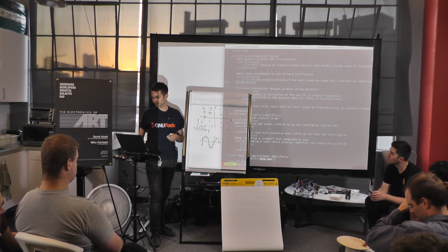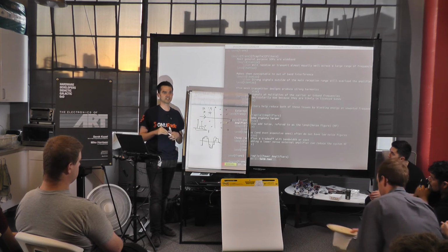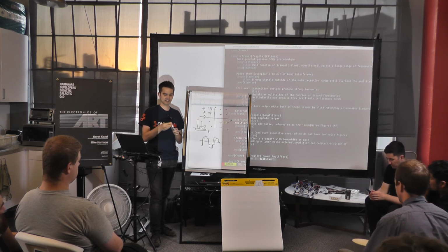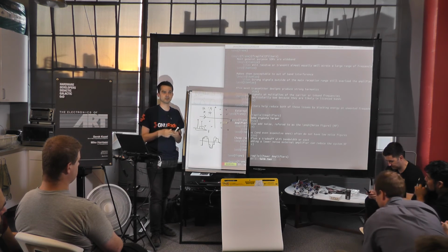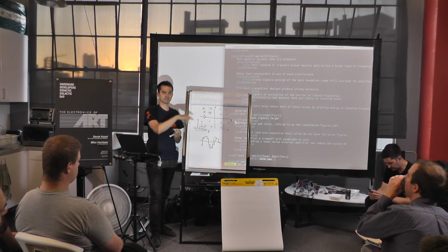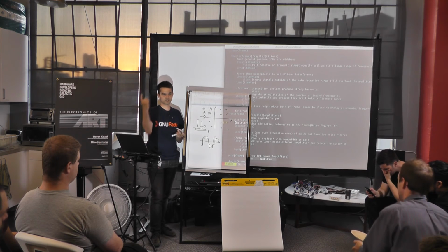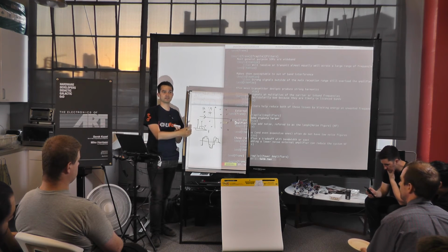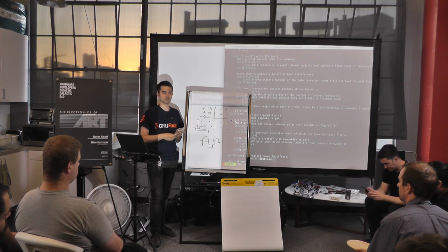Filters, amplifiers, especially this is a really terrible receiver. It has a lot of its own noise. And so if you put an amplifier out in front of it, a lot of the folks who use these to receive airplane data will put an amplifier and a filter out in front. So they're only looking at the frequencies of interest. And because these are fairly weak signals from airplanes flying around, they'll put in an amplifier that'll increase the level of the signal before it even hits this. And you can get a much better signal reception.